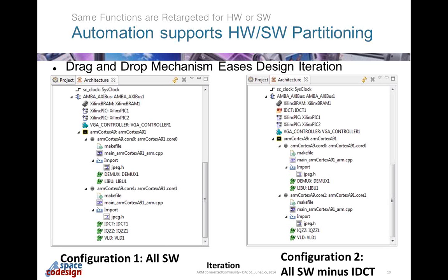An overall embedded SoC design flow with Space Studio is illustrated here. The design process starts with a C++ function for your application, or specification for your application. It enters Space Studio as a multitask functional specification or algorithm whose behavior is validated in our ELIX module. The working algorithm is then mapped into specific architectures involving processors, interconnects, peripherals, memories, etc. in our SimTech module, where design exploration is carried out until you converge on an optimal hardware-software partition that meets your specifications, such as performance and power.